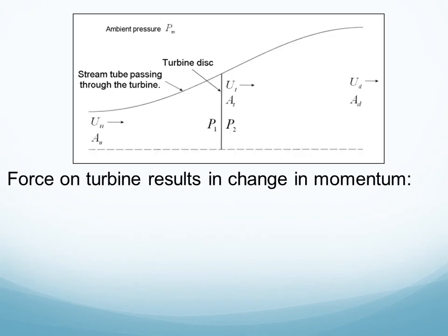So as you can imagine, we have this air current hitting our idealized actuator disk and coming to a stop at the base of the disk. This sudden change in velocity of the air current exerts a force on the disk and experiences a change in momentum. The force can be calculated by multiplying the mass flow rate of air times the change in velocity, and so I think a quick unit analysis here is helpful.